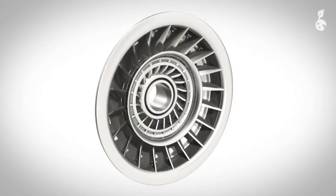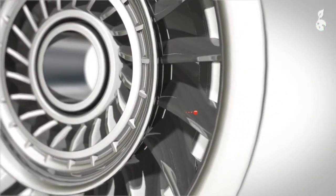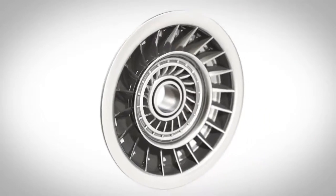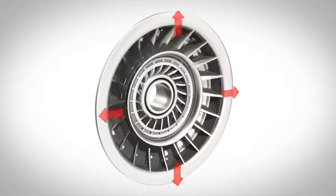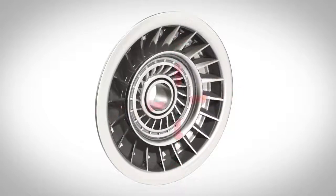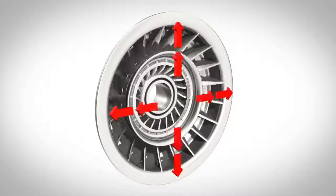The first part of the torque converter is the impeller. It has curved blades and is filled with fluid. The impeller spins. The fluid will be thrown outwards by centrifugal forces caused by the rotation of the impeller. The faster the impeller rotates, the higher the centrifugal forces.